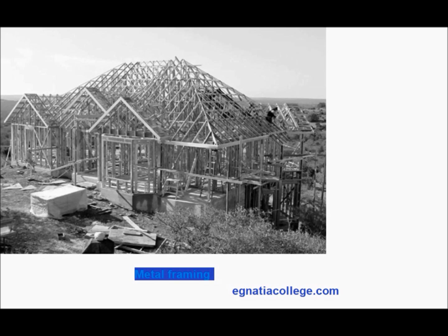Unlike wood framing, steel framing uses tracks and runners in place of bottom plates and top plates. The lighter, less expensive grades of metal framing are not as strong as wood, so they are used primarily for interior partitions or in conjunction with other structural materials. Metal framing can be pre-assembled just as you would pre-assemble wood framing.